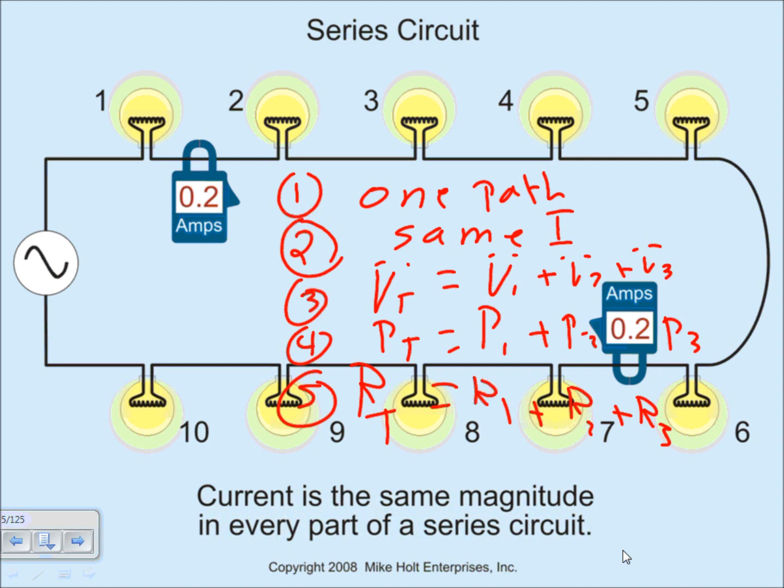And that's what we designed in this panel. For the most part, the voltage in this panel is 120/208. It doesn't go from 120 to 10 volts. The voltage stays the same, and what fluctuates is the current. So the series circuit cannot give you that. Does the voltage fluctuate here with the load? As you add more or less load, the voltage across the load fluctuates. At one time you might have 10 volts here; add another load and this will go to 20 volts. Bad news. We don't design equipment for this, for the most part.